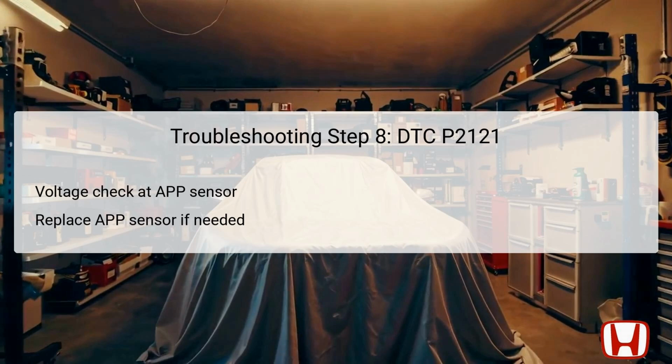After switching the vehicle to the on mode, it's critical to measure the voltage at the designated test points. A target reading of around 5.0 volts is expected. Achieving this indicates that the sensor is receiving adequate supply voltage. If this is confirmed, replacing the accelerator pedal module is warranted, as it suggests the sensor itself is defective. If not, follow the protocol to step 9 to check other lines indicating potential issues external to the sensor.